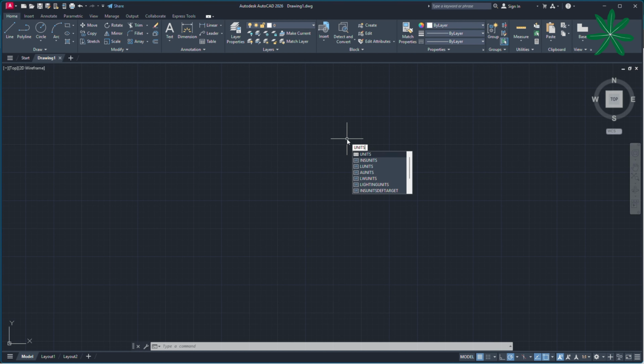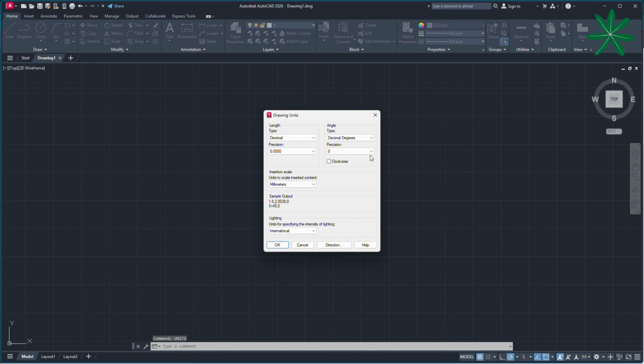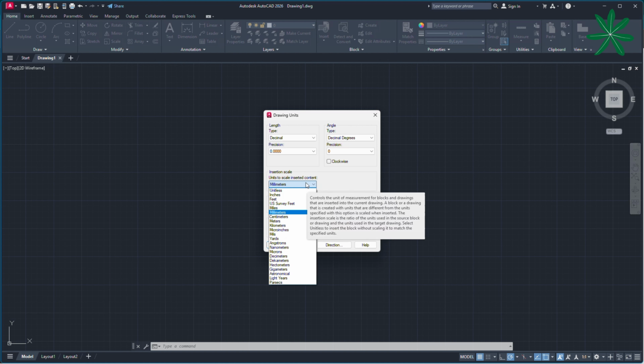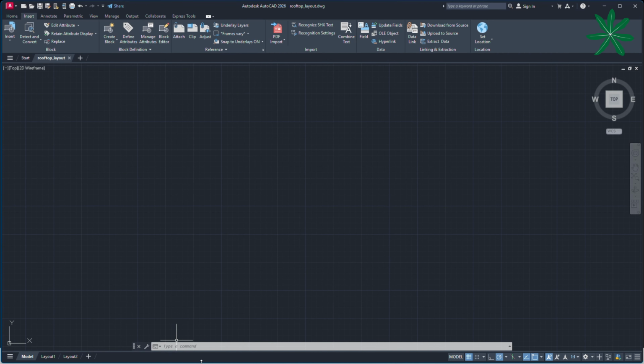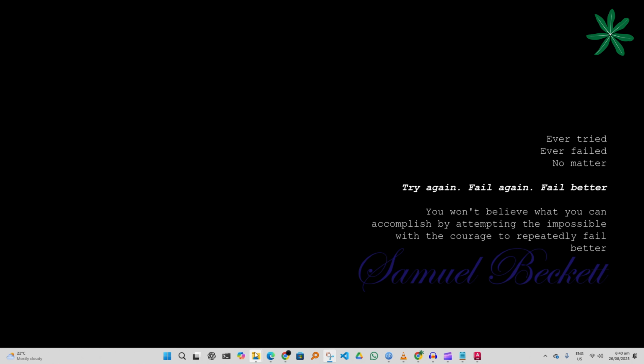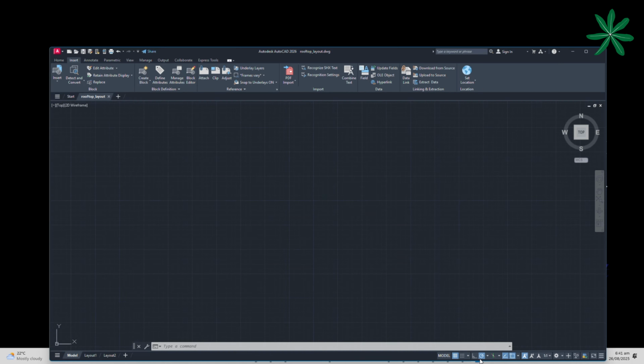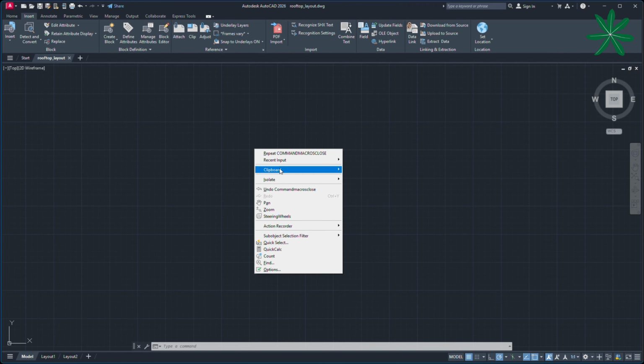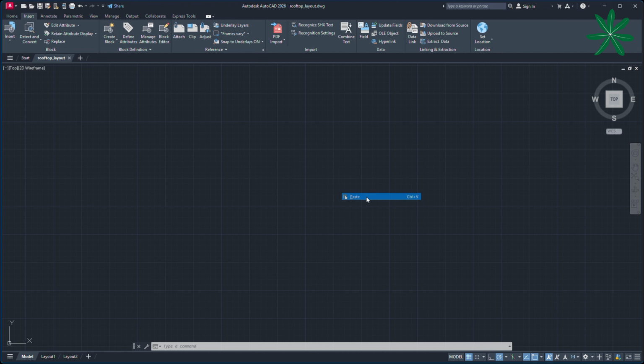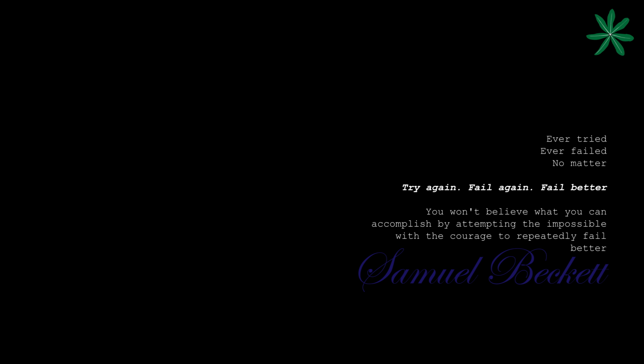As always, the first step is to set the drawing unit. In the next step, we would go to our folder and import the map we saved in step 1. Now we copy it to the clipboard, come to AutoCAD, right click and paste it. Now you specify the insertion point. As always, we would insert to the origin, so we enter 0,0. Leave the scale factor at 1.